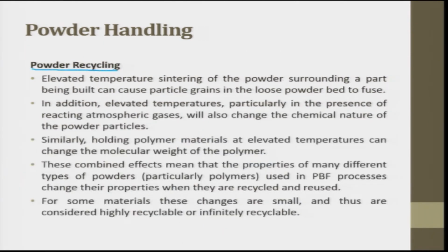Powder recycling is one of the biggest issues. The moment you use powder in the development chamber, the two side cartridges will have the fresh powder, and in the center the fresh powder is spread and cured. After the part is made, the powder in the center development table has to be removed.